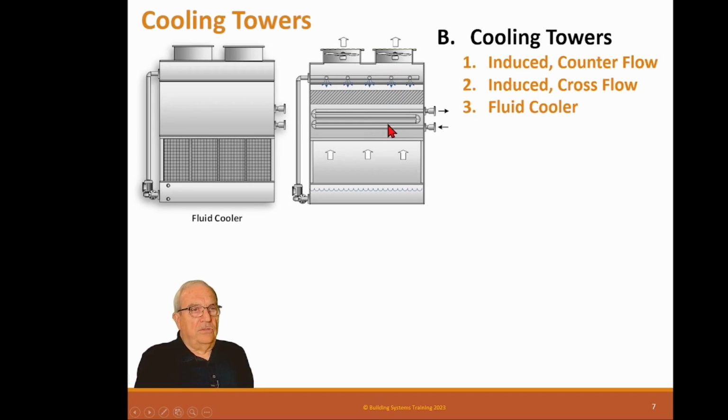And the reason I don't use these everywhere is because, one, they're expensive because this heat exchanger runs the price way up, and two, these don't last forever, because a normal cooling tower will last 20, 25 years, not too much beyond that, unless it's a hand-built-up tower.